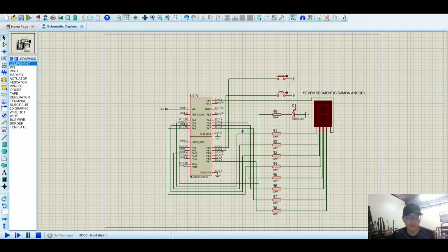Now I will explain the schematic diagram for the carpark system designed using an ARM Cortex-M4 microcontroller, STM32L432KC. The 7-segment display, configured as a common anode, is connected with physical pin mapping on the Nucleo board as follows: A PA1 A1, B PA10 D0, C PA2 A7, D PA3 A2, E PA5 A4, F PA6 A5, G PA7 A6, and DP PB7 D7. The display shows the number of available spaces 0 to 9 and FULL.